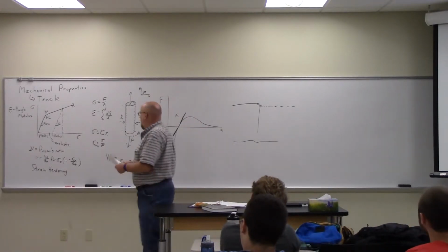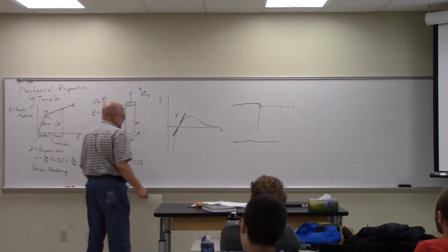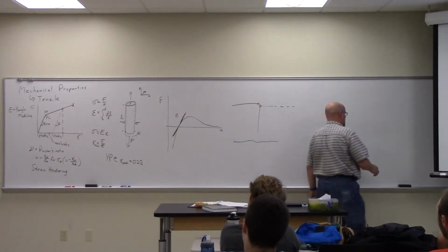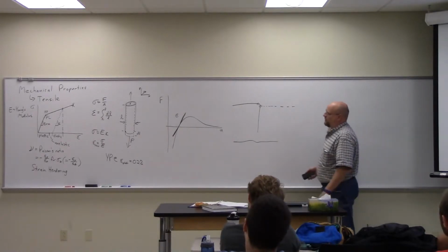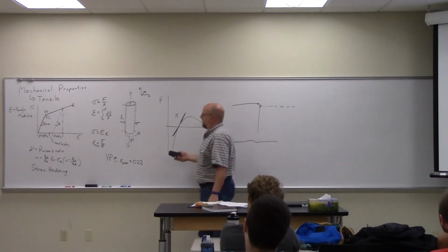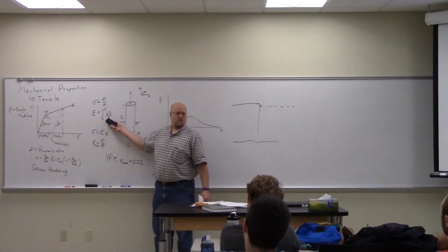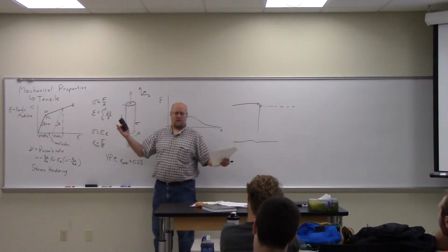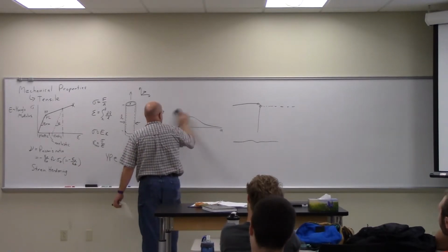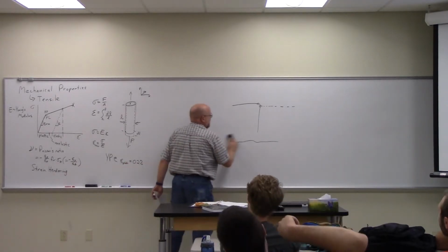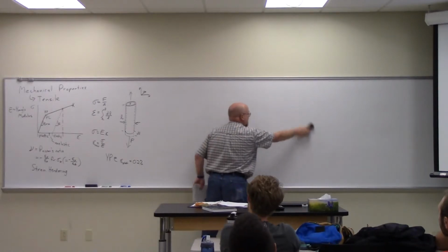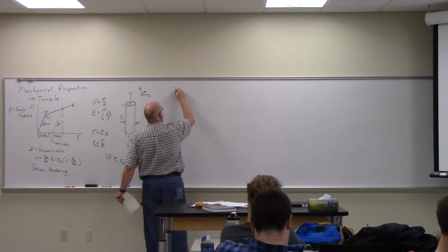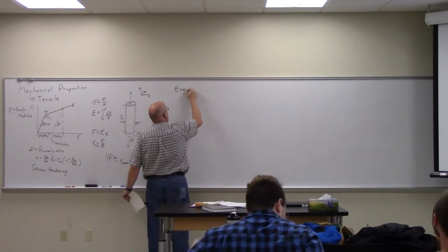All right. So all of this is sort of good, what I would call true stress and strain, or what is called true stress and strain. However, it's going to be really hard with a real material to do an integral of some measured quantity, right? That's going to be kind of impossible. So instead of true stress and strain, we generally work with engineering stress and strain.